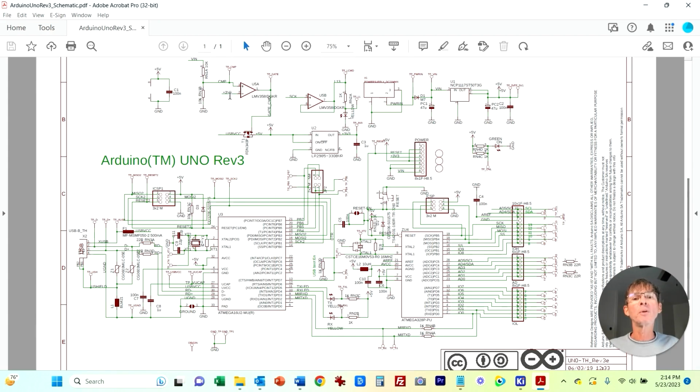That 3.3 volts is actually also used here, and this is really an op amp, but it's operating like a comparator. I'll go over this in detail, but this circuit's just looking to see if you've got a separate input power supply. Then it will flip a switch and choose one of the power sources. Then this other op amp is connected up and is basically serving as a buffer, just to drive an LED. Once again, I'll go over that in more detail.